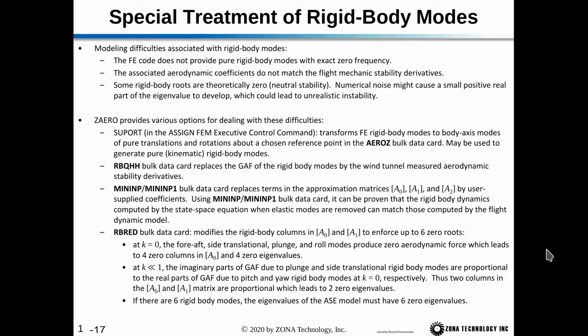Next, we have special treatment of the rigid body modes. So the modeling difficulties associated with the rigid body modes are: one, the finite element code does not provide pure rigid body modes with exact zero frequency. Next, the associated aerodynamic coefficients do not match the flight mechanics stability derivatives. And finally, some rigid body roots are theoretically zero, which are neutral stability. However, numerical noise in the RFA procedure might cause a small positive real part of the eigenvalue to develop, which could lead to unrealistic instability.